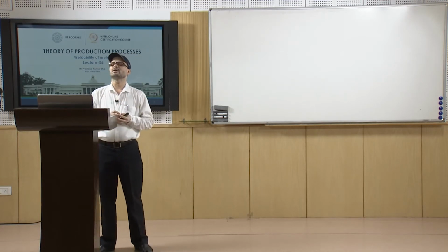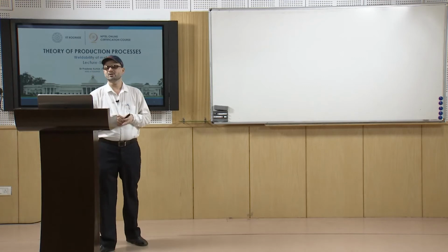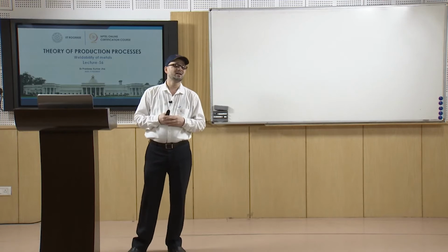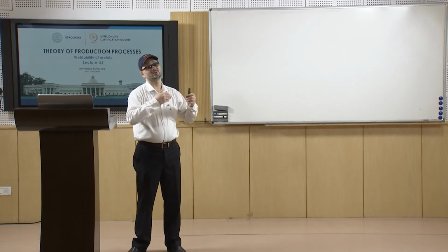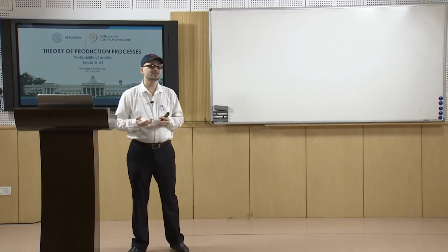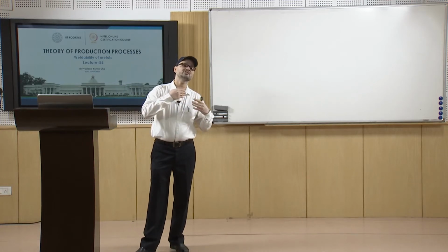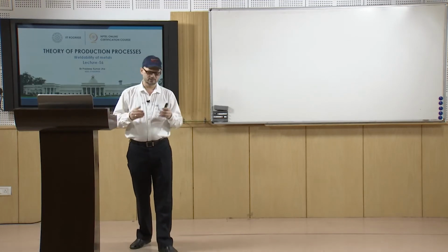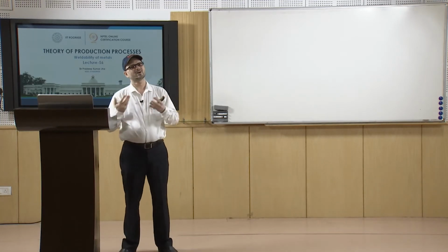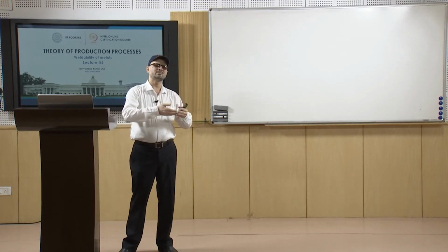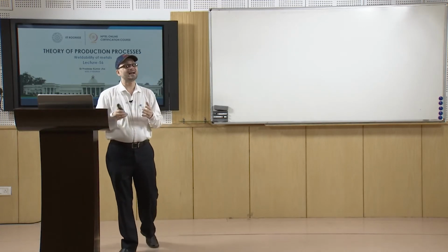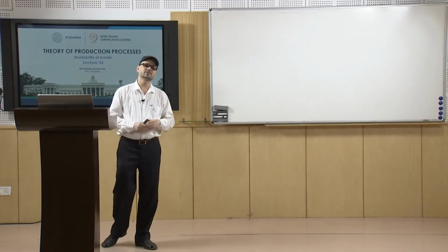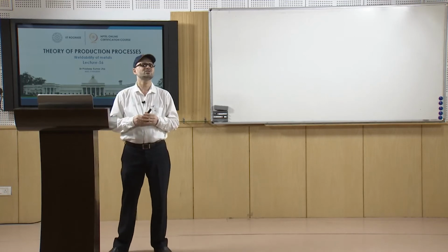That is known as metallurgical compatibility, because many a times, if it is not metallurgically compatible, it may lead to different sets of phases which may give you undesirable structures or undesirable properties, like the formation of different types of carbides, or undesirable very hard phases. So, that will basically affect the property of the material or the welded joint.